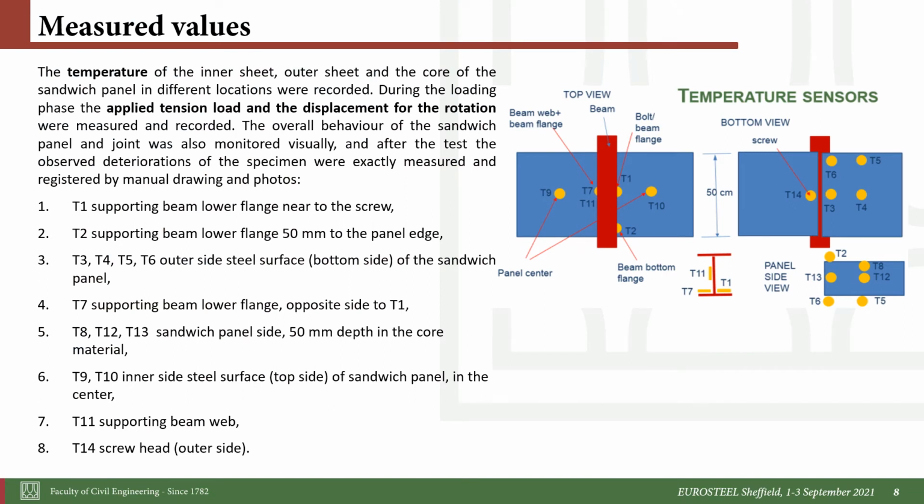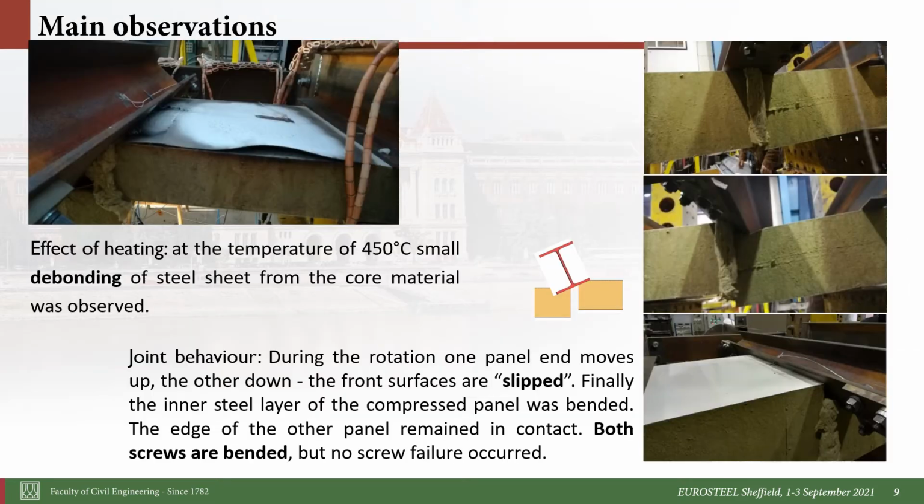During the test, we applied plenty of temperature sensors. You can see the dots here inside, outside of the panels, and the I section as well. And of course, we measured the rotation, the axial force, the horizontal movement and the displacement as well.